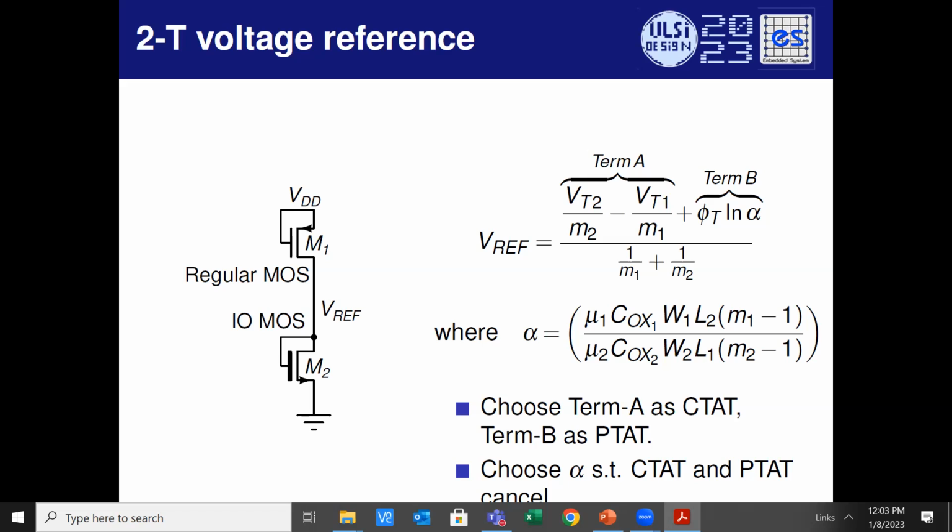Always go back to the CMOS inverter, right? PMOS, gate is at VDD, source is at VDD, drain is at ground, then there will be leakage because source to drain voltage is large. If source to drain voltage is 0, then there is no way current will flow, leakage or not.